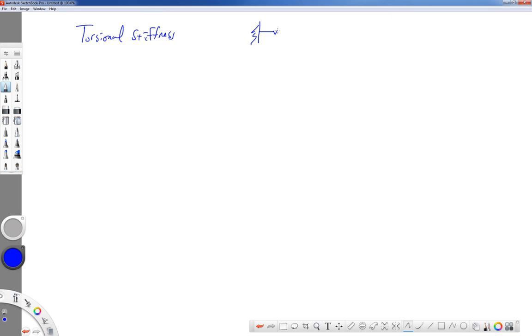If I have a spring and I apply some force to it and I measure some displacement, if it's a linear spring, we say that that spring has a stiffness that can be determined by rearranging the formula F is equal to Kx, or delta X. And we say that that K is the stiffness. If we look at this expression, on the left-hand side we have a load term, and on the right-hand side we have a displacement or a deformation term.